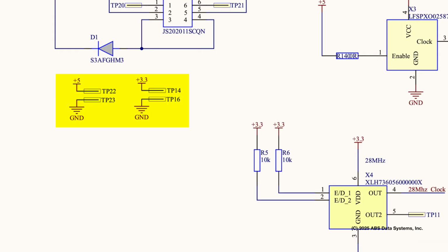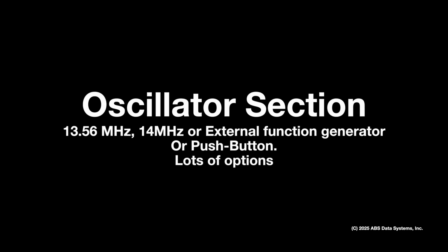I've added test points for the power supply in both the 5 and the 3.3 volts. I found that sometimes you want to experiment with other modules or components, and you need a way to supply power to those parts or modules. Therefore, I've exposed both power sources.